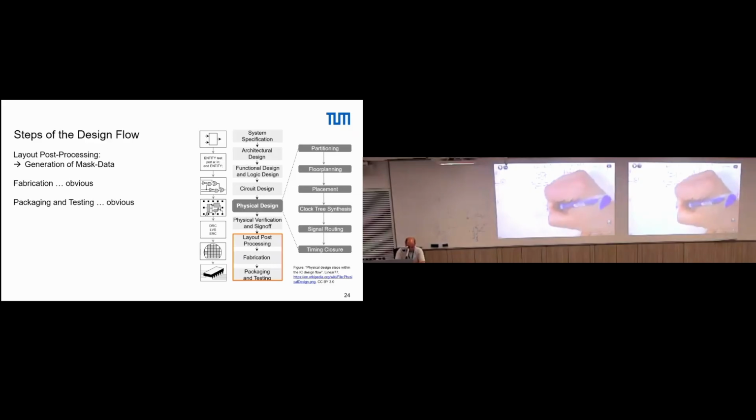And that's effectively where the magic is. You have some memory here, some SRAM at the end, which is programmable. So without the values in place, this is what you receive from your FPGA vendor. Then you can select what your inputs and outputs are, and you can select what is programmed in this memory. So in our case, we want to implement an AND gate, meaning if we have A at 1